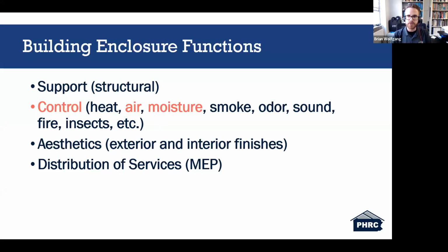Like I said, sometimes these are aligned. Sometimes in order to complete the installation of a water resistant barrier, you'll include a tape that also serves as an air seal. Other times you'll include a tape that really doesn't have as much to do with establishing a drainage plane in your wall assembly, but is really just there as an air sealing measure or a belt and suspenders above and beyond air sealing measure because you're trying to reach a loftier than code minimum goal.